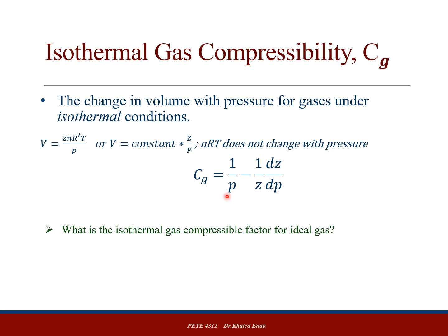PT diagrams, the phase diagrams that we studied in chapter 1, when we had, for example, reservoir A, we had two paths. The first one was straight, isothermal, going down, pressure drops. And the second condition was going left, the second path, which is decreasing pressure and temperature, going from reservoir to the surface. So the pressure and temperature both change.